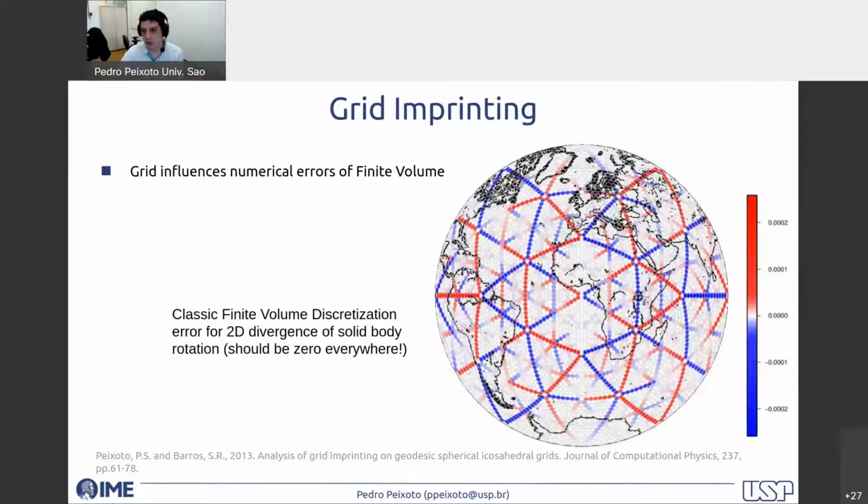So this is a more or less high resolution grid. You have small cells here, but you can basically see properties of the coarse grid, right? This is called grid imprinting. A lot of the times when you do simulations with MPAS, you will notice some kind of grid imprinting, which means that some places in your simulation will give errors which are unexpectedly high, and it's nothing to do with the physics, it's only to do with the grid, right? So this is something to be aware of. It's called grid imprinting.